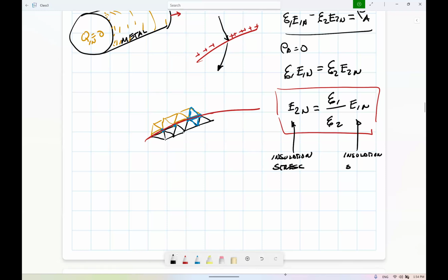Well, Professor Francisco, this is interesting for me because we use this ratio to try to control the electric field in surfaces of insulators, for example. We can modify the properties, the normal components, and maybe reduce the tangential component of the electric field, which is the most important in insulators. So exactly, by this condition, we can modify that ratio between tangential and normal components.